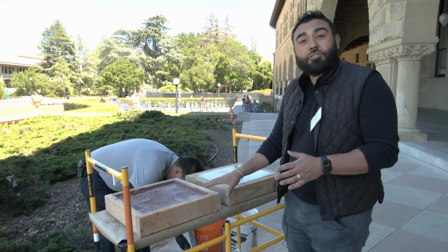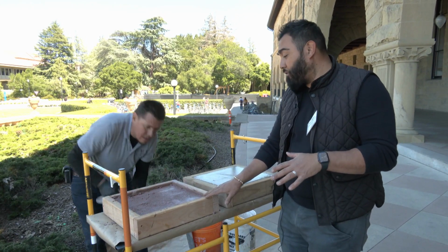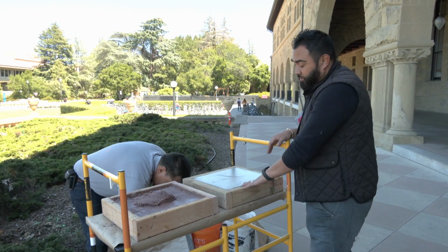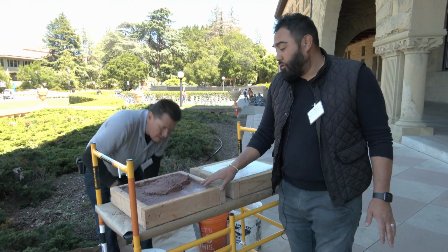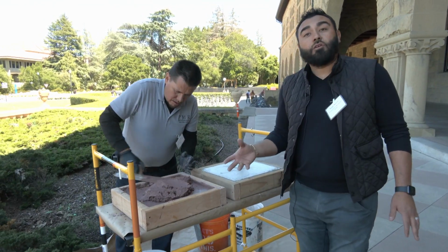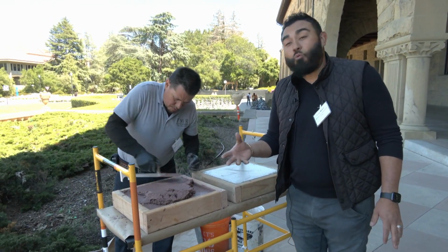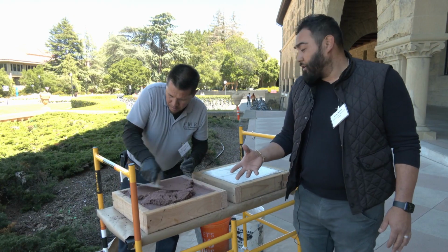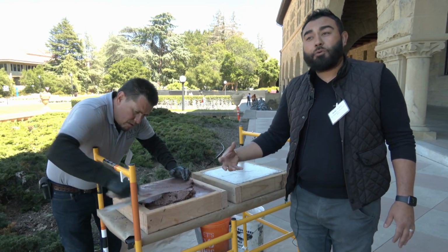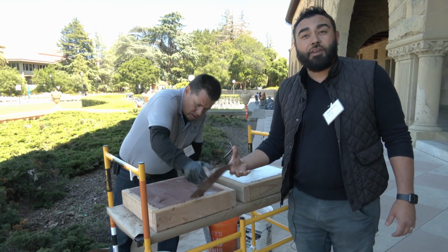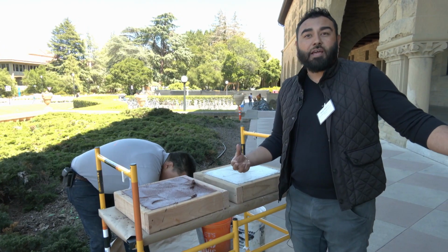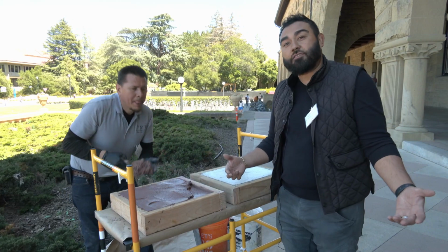We let the paver cure for 3 to 5 days, just like you see we did here earlier today. Once the paver has cured, we come back and use a wet honing system with a cup wheel to expose the aggregate and give it a natural patina finish that the original pavers have accomplished in the last 100 years.